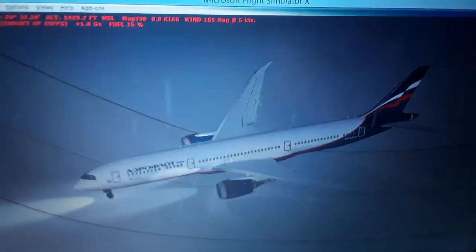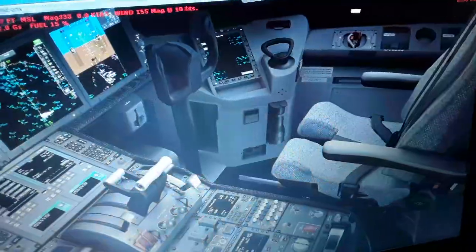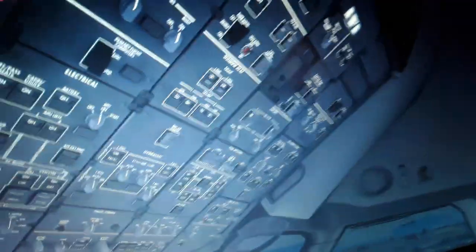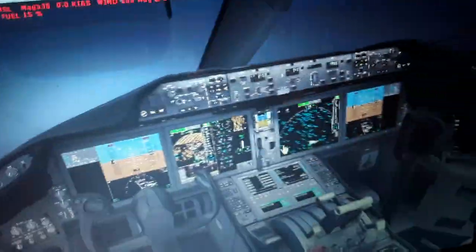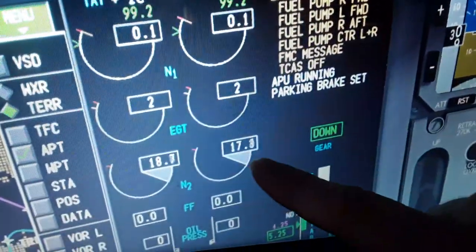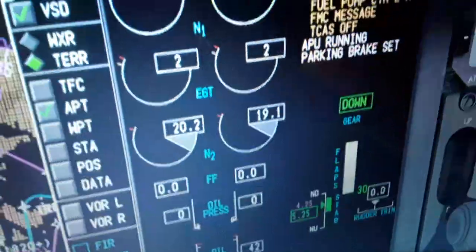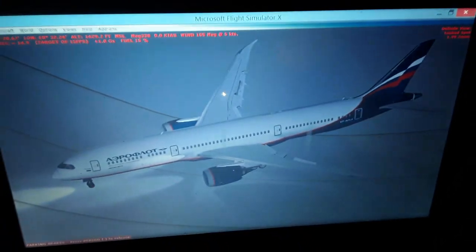So you can see over here the engines are off, so we need to restart them very quickly. Over here both auto start in the on position like this. So you see the amber switch lights on in the overhead panel for the auto start. So we have pressurization right now into the engines. The N2 only receives pressurization for the engine starter, so above 20% of pressurization, 20%.